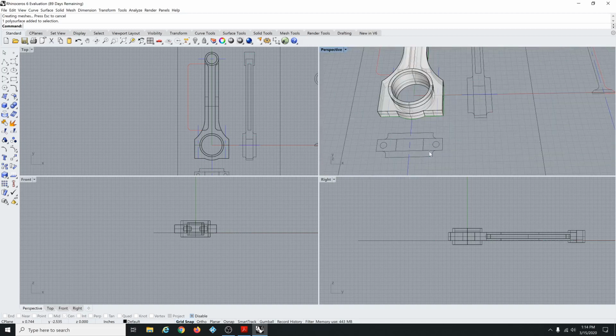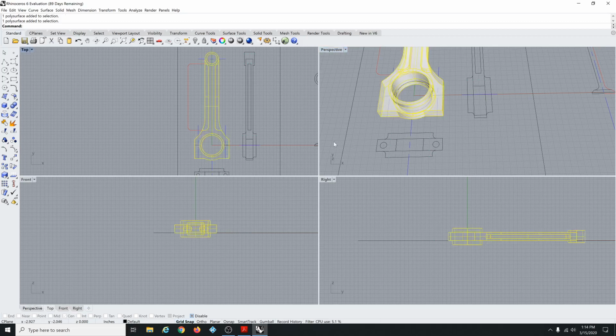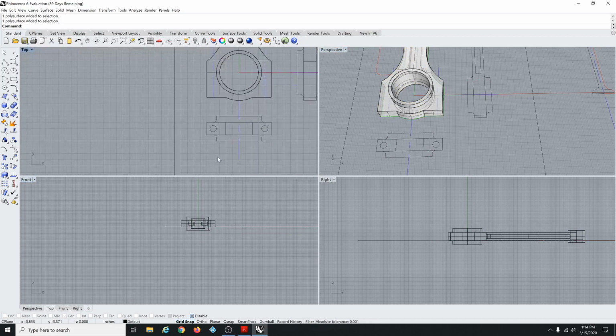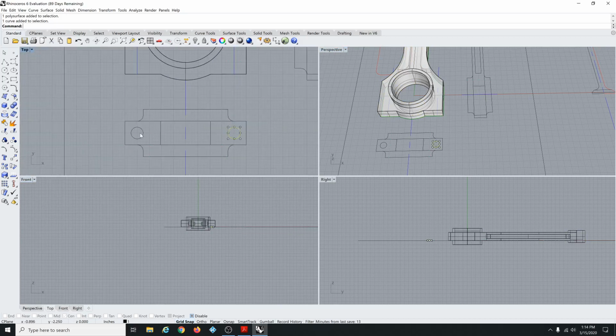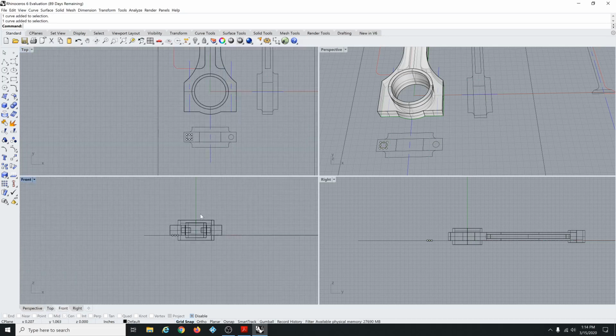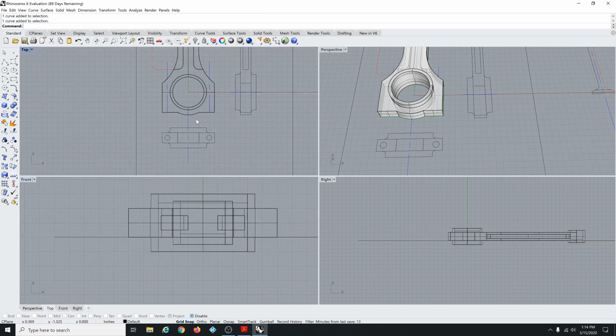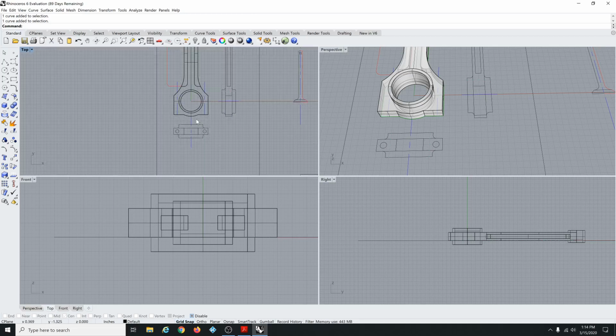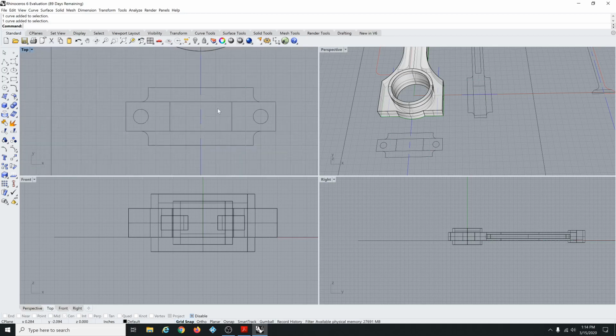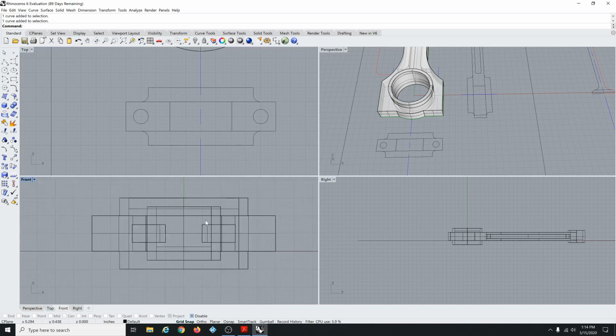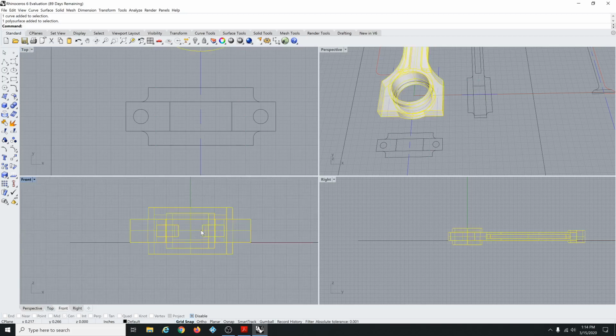So we have to cut these two holes here, and then split the body of this thing, and we're done. Just looking at the end view here, I can see these two holes. So I'm going to draw those in the front view window. Just keep this all straight here. Right up here in the top view, I'm looking at a 3-view ortho, but I want to line that up with the actual 3-dimensional volume in the front view.